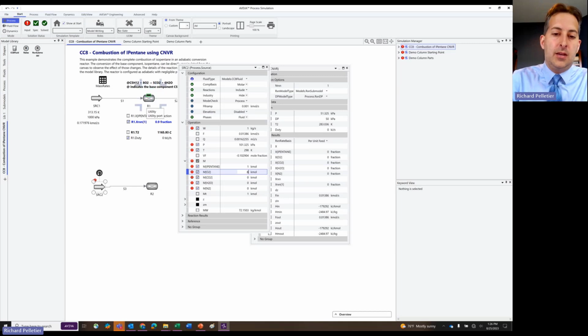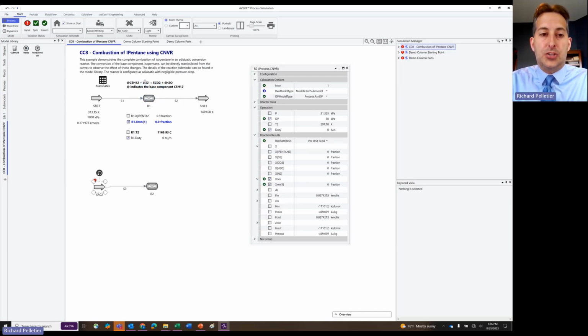So let's add 8 kilomoles of oxygen. Now I should have sufficient reactants in order to do a reaction. Right, so now we're going to change this over, and we can go straight to 1 for 100% conversion. We can go to some value in between. It's probably safe that we start off slow and just make sure that it solves. All right, so we do 10% conversion. All right, that worked out just fine. Let's try maybe 50%. Oh, no problem.